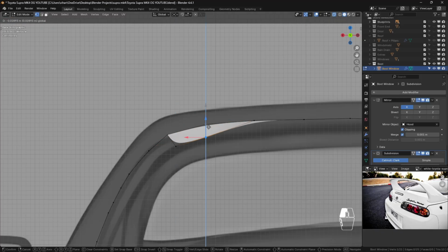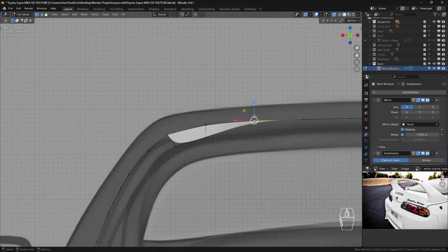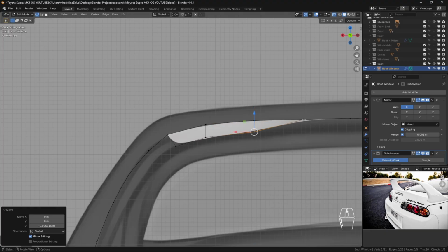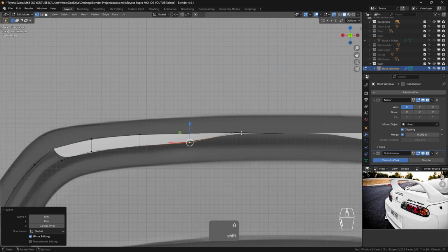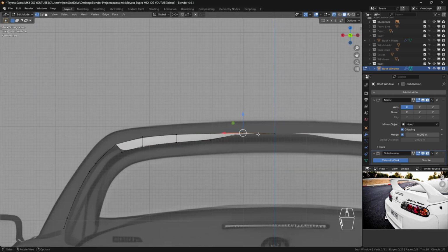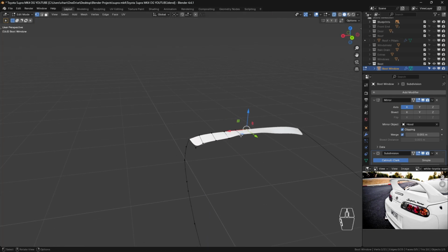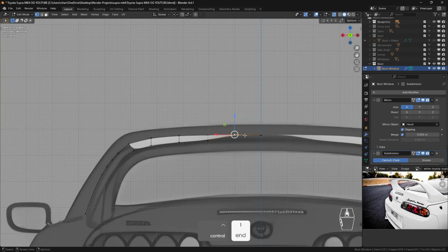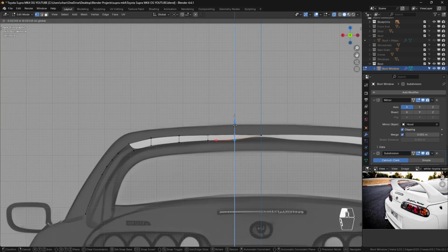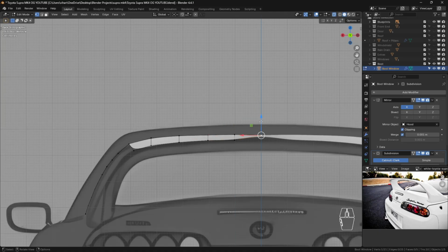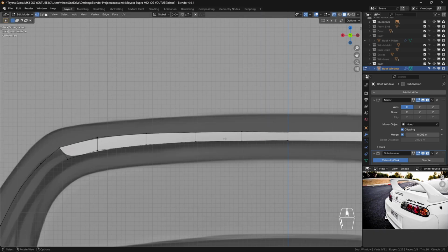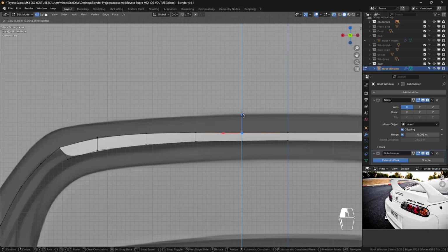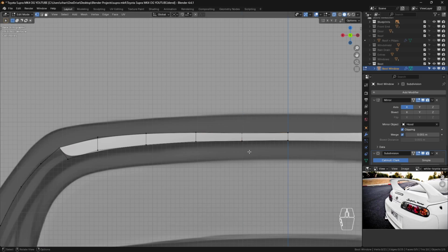And we're going to be doing the same. It's a blurry line, but make sure you select the right vertex. If you don't, you can just go ahead and select it like that. Press Ctrl 1 and come back. Alright, there we go. And just make sure this also has a smooth flowing curve right here.